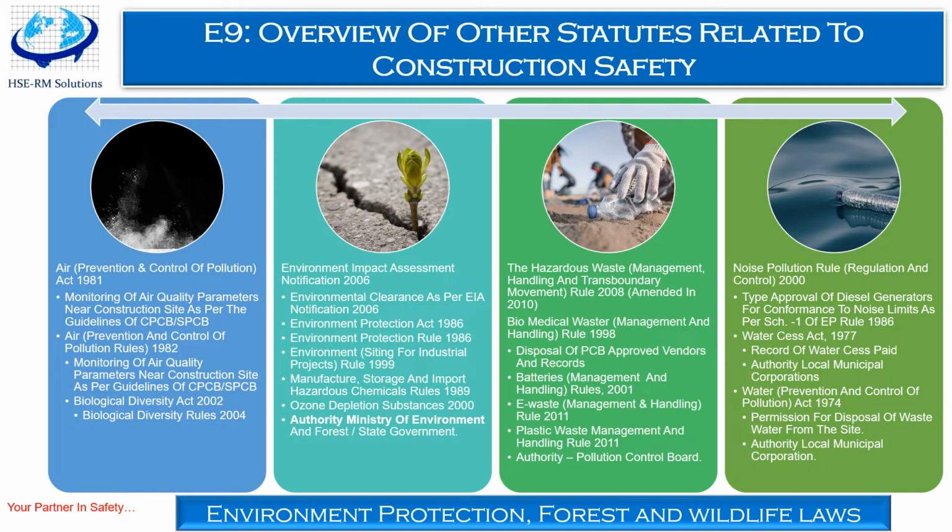You have to do monitoring of air quality parameters near the construction site as per guidelines of the CPCB, that is the Central Pollution Control Board, or the SPCB, that is the State Pollution Control Board. This comes under your legal requirements. So under the Air Prevention and Control of Pollution Act 1981, you have to make sure that you are monitoring your site or facility with air monitoring as per CPCB and SPCB norms.